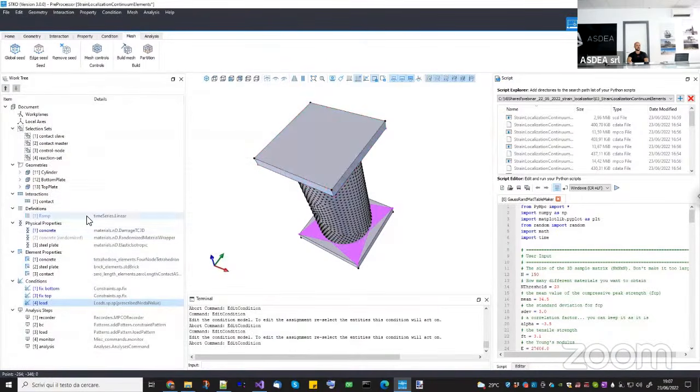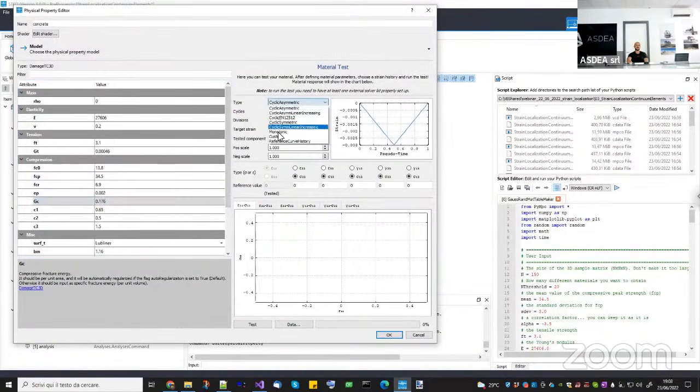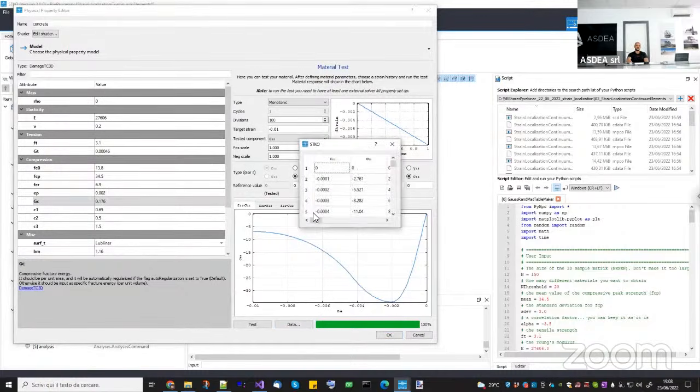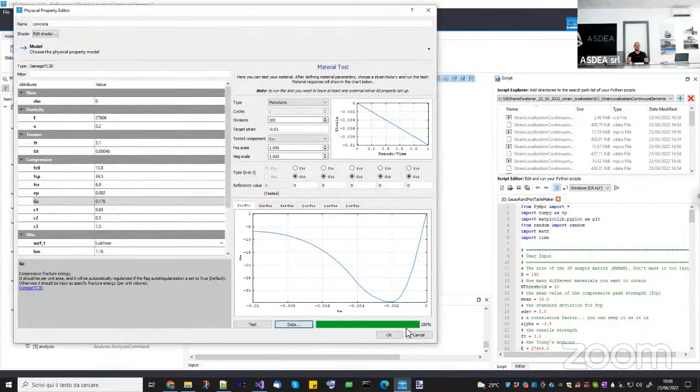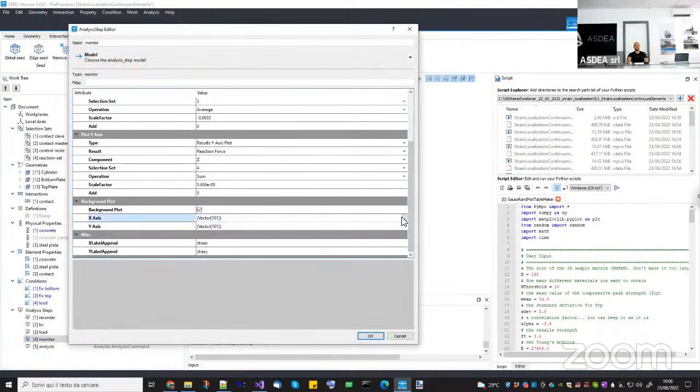3 millimeters simply because what I've done here was to start from this material model. Let's say the Chinese code tells me that this is the fracture energy that I have to use, and I want to see what I obtain. So I go here, I push it up to 0.01 compression. This is the curve that I obtained following that code. Okay, so I went here in data, I extracted the epsilon 11 and the sigma 11, and I put them here in the monitor as a background curve. I changed just the sign, so I made them positive.